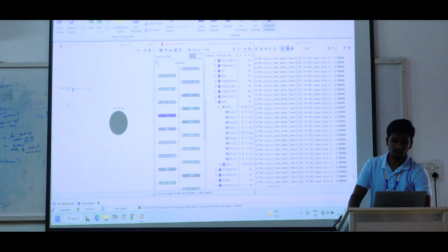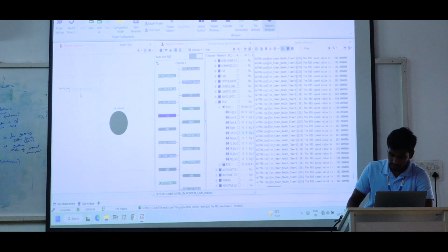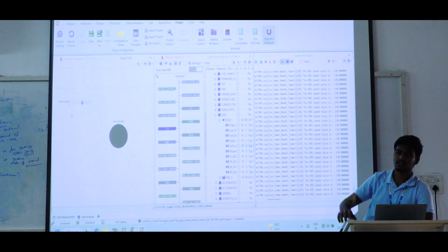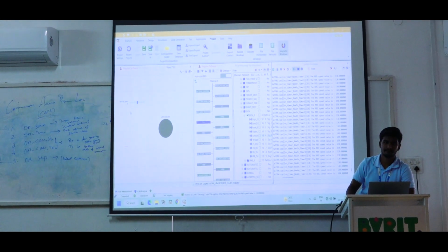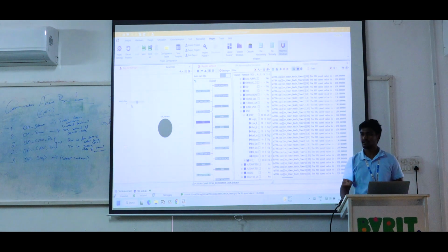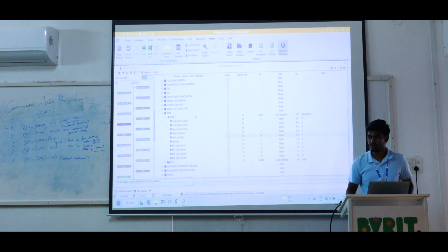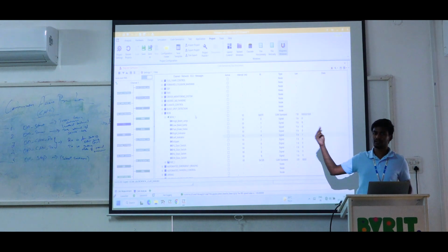Now you just increase the values from here. For example, you give more than 100, but we are not receiving any values. Right? Now you are giving more than 100, but we are not getting output because in this RBS we have not turned on the BCM node. So this also we need to write in our CAPL scripting. I will explain how to write that.